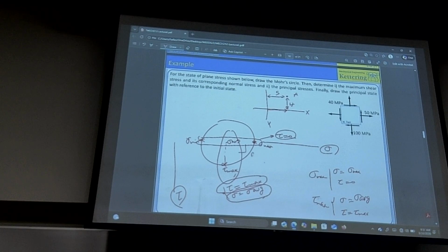On Mohr's circle, this is 90 degrees. But we talked about it because we had twice stated the equation. Really, in practice, it's 45 degrees. So if you have an object and you want to physically or geometrically see which faces are failing, we have two perpendicular faces, either this or 45 degrees.